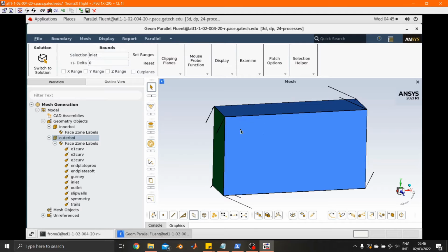So once we've opened up our CAD into the Fluent mesher, and it's going to look something like this, we have our outline where we can see all of our things. We then want to set the sizes for our meshing. So the first thing we do is we create a surface mesh of the 3D model. It's going to create a 2D mesh on all of the surfaces, like the outer box and all of our rear wing surfaces. And we set sizes for each different face.